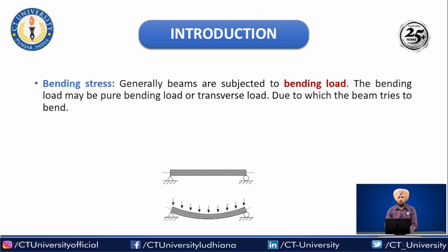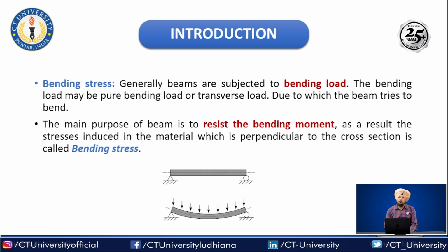The beams are horizontal members subjected to transverse load. As you can see in the figure, the beams are initially straight, and when they are subjected to transverse loading, meaning loads perpendicular to the axis of the beam's cross section, they are subjected to bending load. We call it transverse loading. The beam will have a tendency to bend in this curvature. The beam is initially straight, and due to the externally applied transverse load, it will deflect in the shape shown in the figure. The stress induced in the material due to this type of load is known as bending stress.